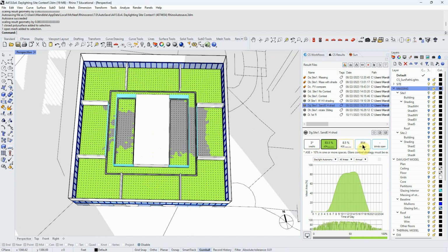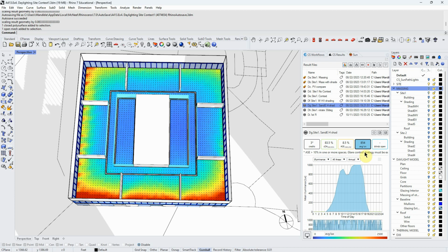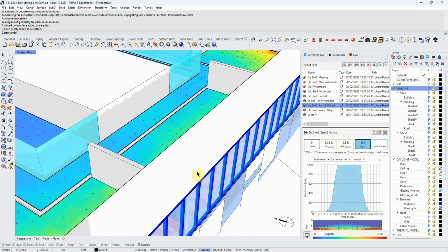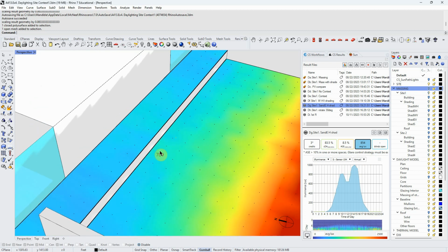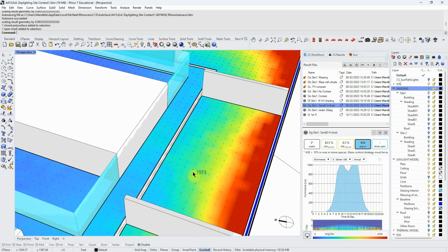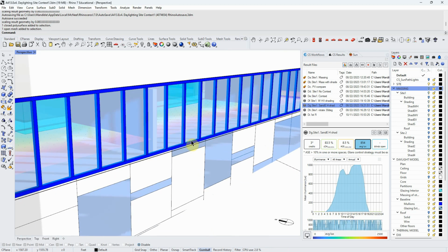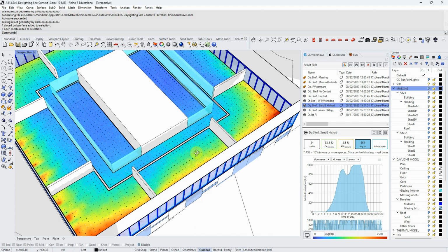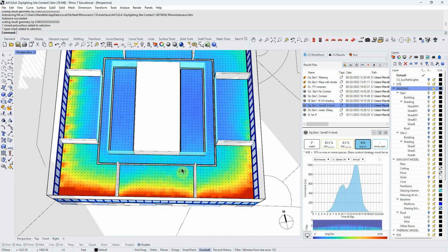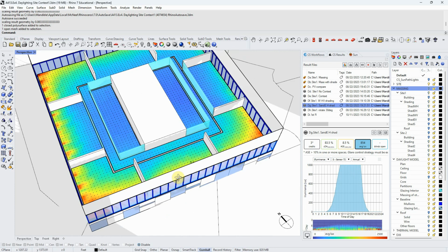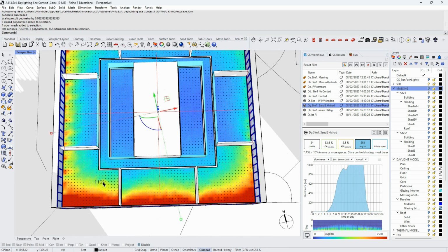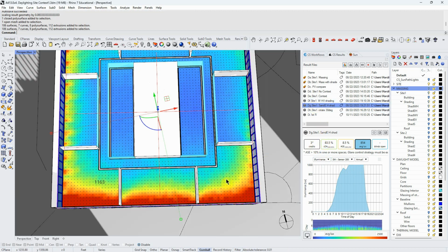So one metric we really didn't talk about much was the average lux. And that's just telling us the average amount of light or illumination on the work surface. Remember, we defined a work surface that was a certain height above the floor. In this case, that was a LEED requirement or a LEED setting. But if this were a gym, for example, our work surface would be the floor, so this would move around and we can adjust it. Any one of these single floor plates could be changed.